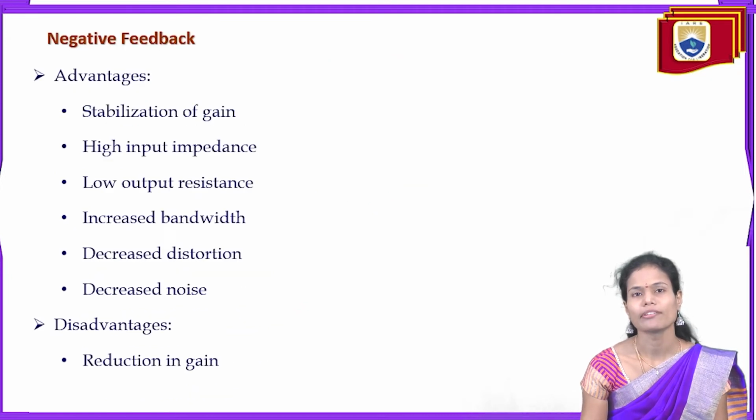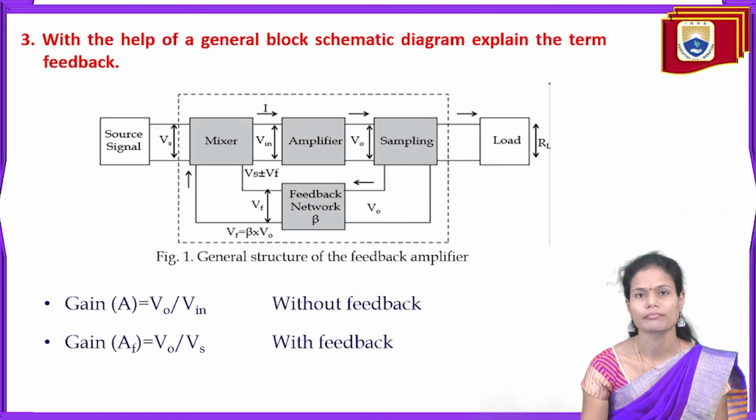While coming to the advantages of negative feedback, it will stabilize the gain, reduce the noise and distortion, and it will improve the input impedance and reduce the output impedance. The only disadvantage of negative feedback is reduction in gain. So these parameters we have to prove mathematically, as it is a long answer question.